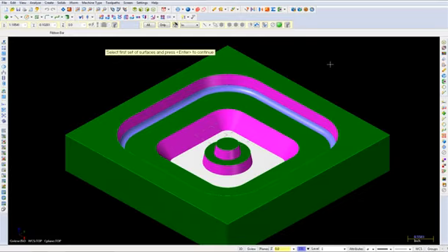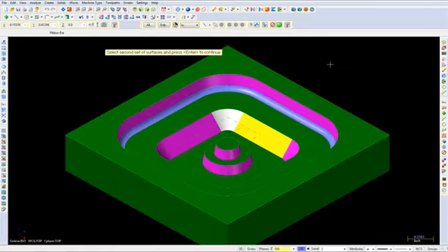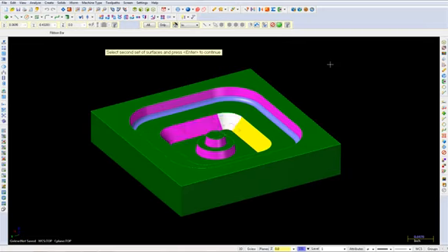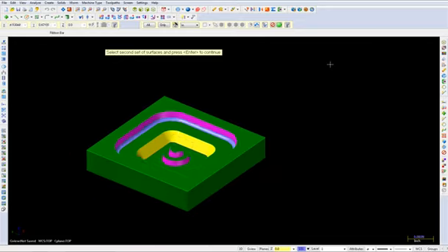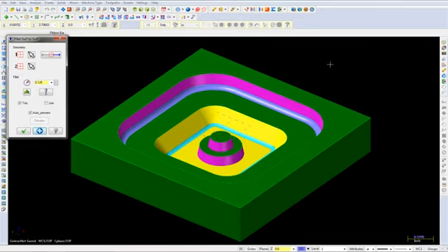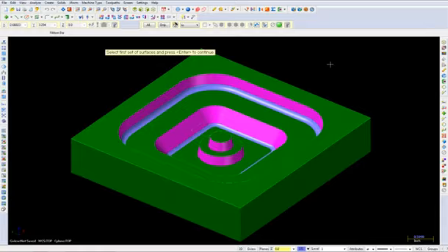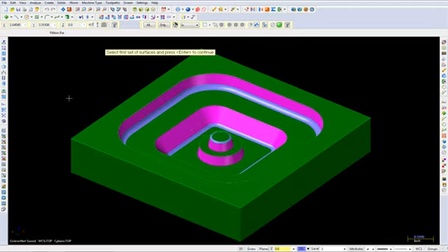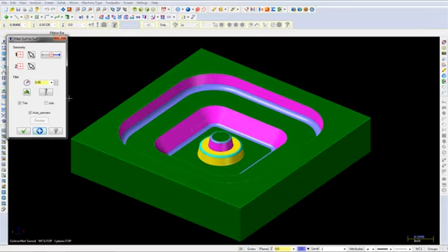Choose this surface here and press Enter, then choose all of these surfaces that I'm selecting. Press the Enter key. Ensure your fillet radius is set to 0.125 and select the Apply button. Then choose this surface, press Enter, and the surface below it, and press Enter, and change the fillet radius to 0.05. Select the Apply button. Then choose this surface, press Enter, and this surface, press Enter. Ensure your fillet radius is also set to 0.05.